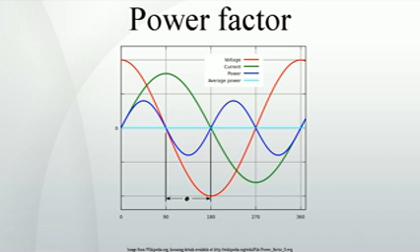Non-sinusoidal components. Nonlinear loads change the shape of the current waveform from a sine wave to some other form. Nonlinear loads create harmonic currents in addition to the original, fundamental frequency, AC current. Filters consisting of linear capacitors and inductors can prevent harmonic currents from entering the supplying system.